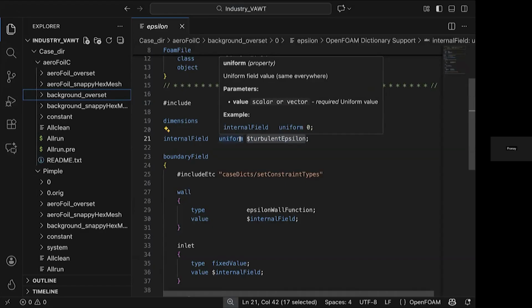With that very small time step, our objective is to contain the CFL value, the Courant-Friedrichs-Lewy number, to 1. Since this is a transient simulation, we need a CFL value less than 1 for the solver to progress and capture the flows correctly.